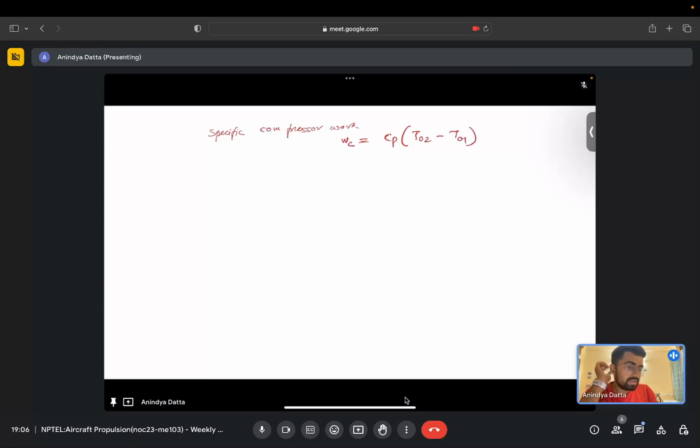Okay, so note here we are now approximating a real cycle, which means we will deal with stagnation temperature. This is 1004. Okay, not just in this problem it's set at 1004, not the standard value 1005. So T02 is 890.4 minus 288. Okay, so 890.4 minus 288 into 1004. This will come out as